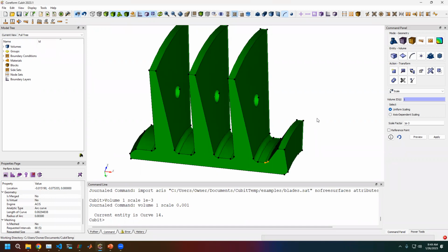So it's one trick that I see a lot of times with highly curved geometries, that they'll have some small curves or small surfaces that are really close to the absolute tolerance. And so the scaling is something that needs to be done. Anyways, I went a little bit deep on that, but I thought that's one big trick that I would recommend if you're having some issues: look at the scale of your model.